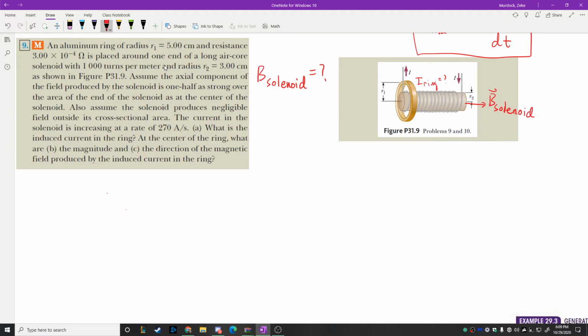Based on the direction the current is flowing, like the current's going this way, it's going around in that direction. So if you wrap your fingers as if you were gripping this tube with your right hand, so that your fingers would be pointing this way, then your thumb would basically point that way. Your hand would be like this. It's a really crude hand, but hopefully you get the idea. That's the direction of the magnetic field.